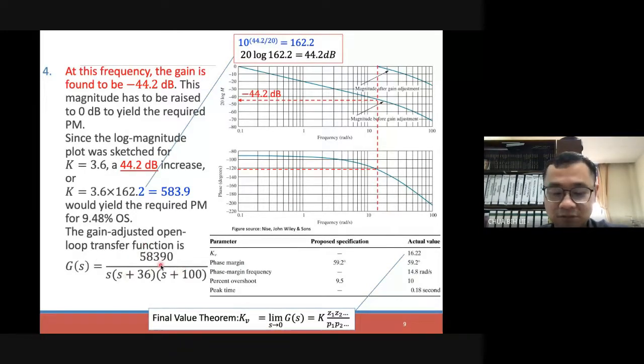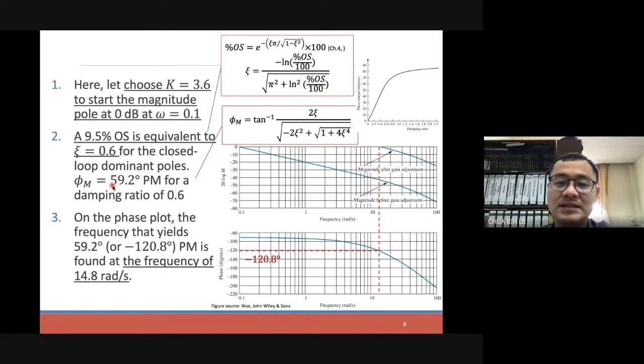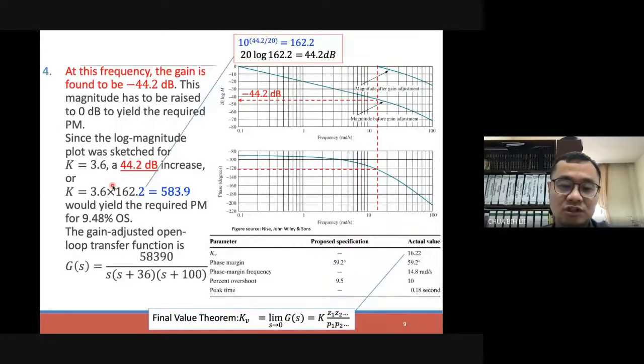So in the final exams or maybe in the test on that day, sometimes you may see that in the question they write, the given open loop transfer function is this. It doesn't necessarily mean it is open loop, but it means you have a transfer function here with a unity feedback. That is how you can interpret the questions.